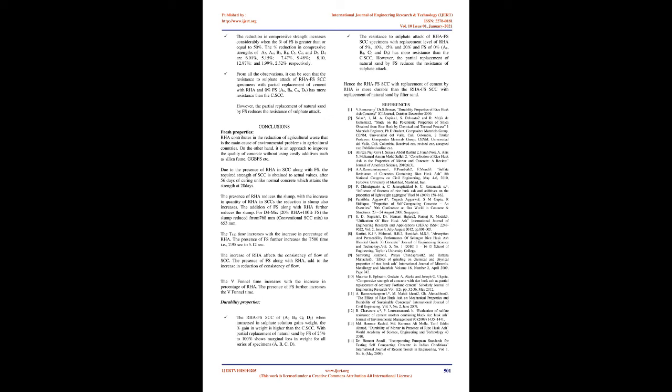Sulfate resistance. From the table, it is observed that C.SCC and RHAFS-SCC, A0, B0, C0 and D0, specimens when immersed in 5% Na2SO4 solution don't lose their compressive strength, instead they show a marginal gain in weight. The gain/loss in weights of C.SCC and RHAFS-SCC when immersed in 5% Na2SO4 solution are similar in 28 and 56 days curing period. However, the effect of variation in compressive strengths is higher in the specimens with 56 days of curing period.